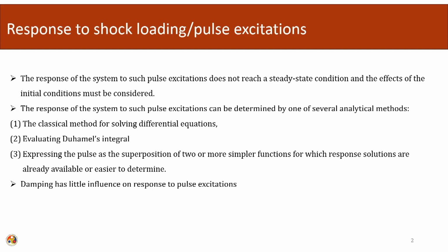So, the response to shock loading or pulse loading excitations. A system responds to such pulse excitation and does not reach the steady state condition, and the effect of the initial condition must be considered whenever we are dealing with shock or pulse type of loading. The response of systems to such pulse excitation can be determined by one of several analytical methods. There are different ones, so we can choose any of them.